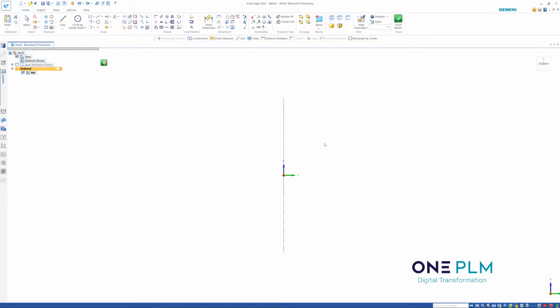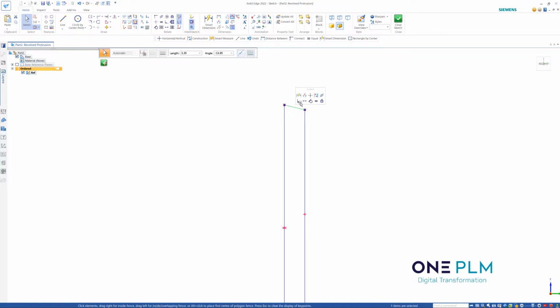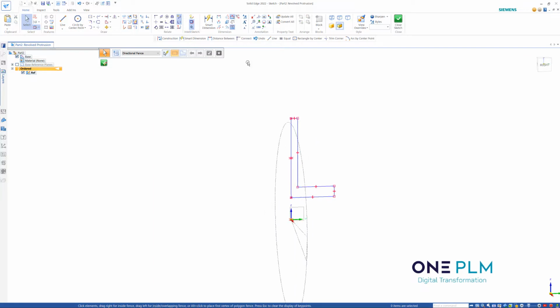It doesn't matter which way we do the orientation on here. So I want the revolve to come up slightly bigger than that circle. That's going to be the depth of our cog. To make sure we don't do that, if we press and hold the shift key, which I forgot to do on this instance, that makes sure that all of your lines become horizontal or vertical. If you do get this kind of error, just use a horizontal vertical. If you're on 2022, you can click on the line directly and choose the horizontal and vertical option on there.